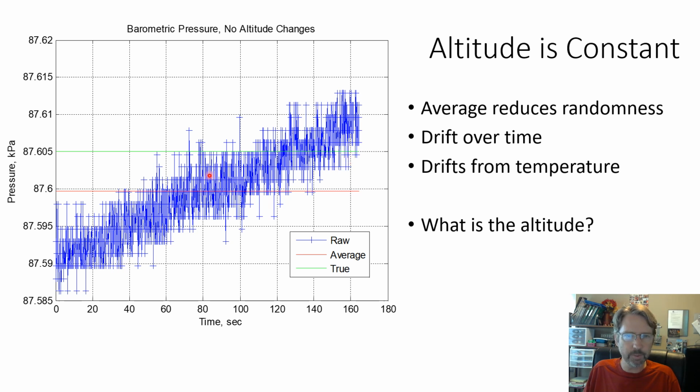And so these are just some of the problems you have to solve. This altimeter was pretty known to drift. It drifted mostly with temperature. So as the electronics warmed up, or if you flew the plane really high where it was cooler up high, you would have altitude change, but it wasn't enough. The plane flew fine. The plane was 10 feet higher than it thought it was. That was close enough for the kind of work that we did.